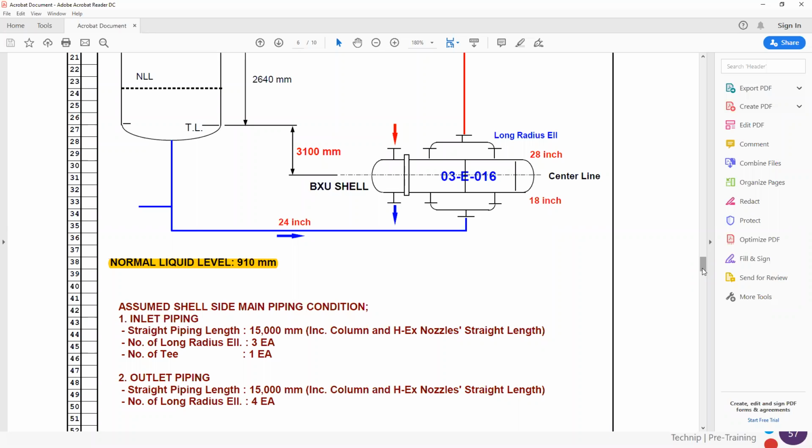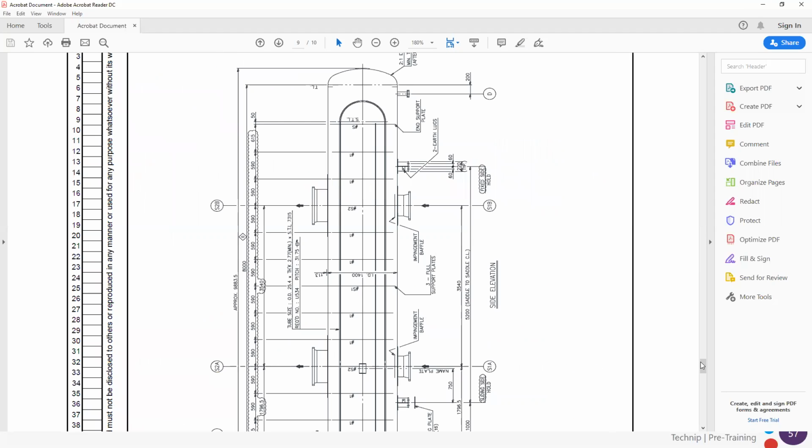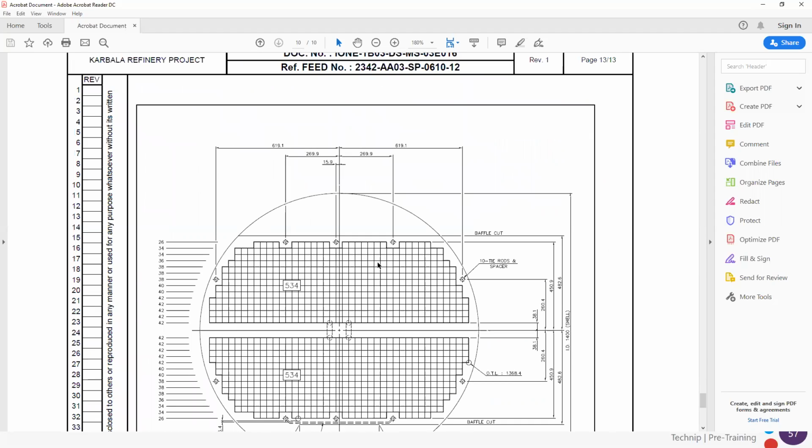It means that my exchanger is easy to clean. I can clean the shell side because I have U tubes and the bundle can be extracted, and I select a square layout, which facilitates the cleaning, actually.